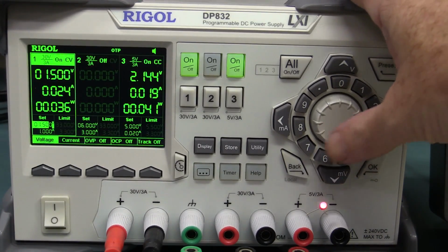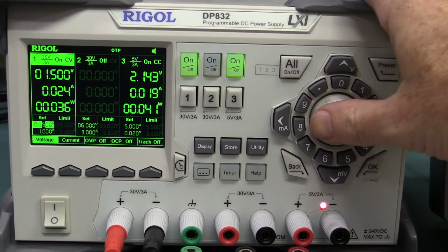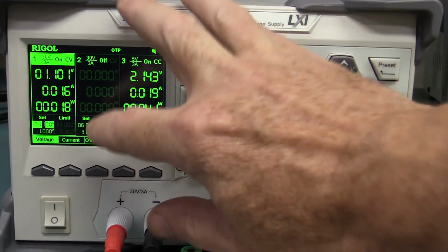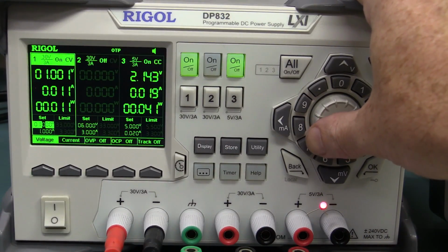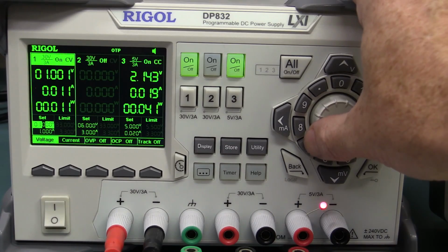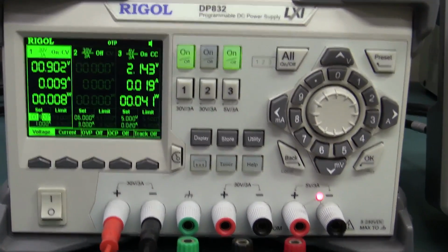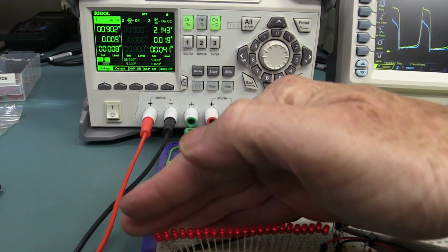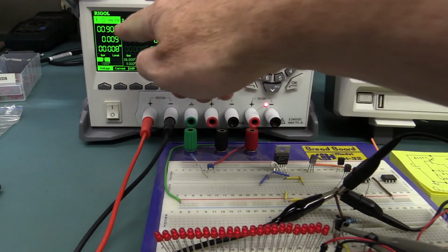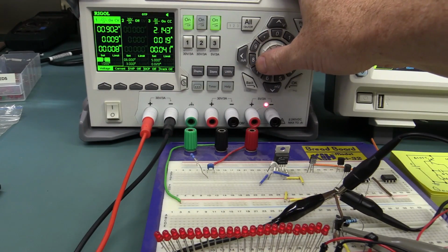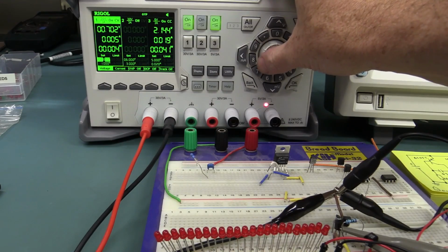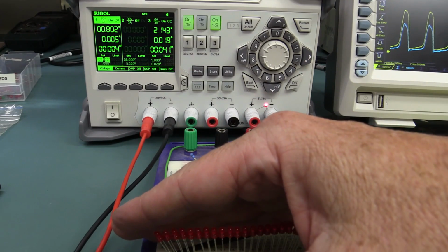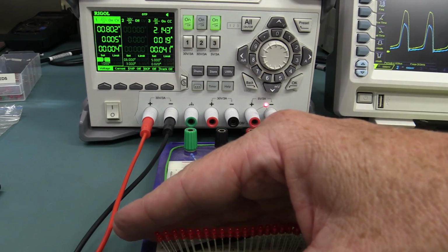And if we go in here and actually drop this voltage down, here we go, I'll tweak it down, 1.4 volts, as you can see, the current is going to drop, and the total power that the circuit is consuming, that includes the LEDs and all the losses. And sorry, I should zoom out there. The LEDs, they're still on, okay? They're still on at 0.9 volts. And drop it down to 0.8 volts there, and they're basically off. That's the threshold voltage of my particular circuit, which is exactly what you'd expect.